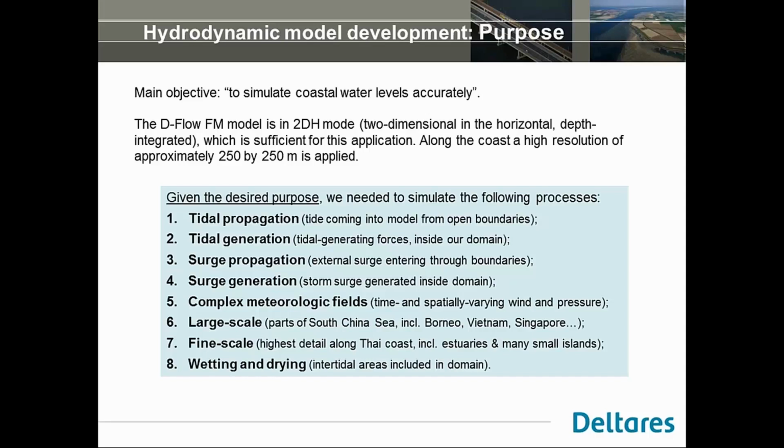We want to capture all the effects of spatially varying meteorological fields. We want to capture both large scale and fine scale. So we want to capture very large parts, geographically speaking, but also much deeper waters. But we want to get to the detail of the small islands along the Thailand coast. And we want to, of course, simulate wetting and drying, since this is a storm surge model.